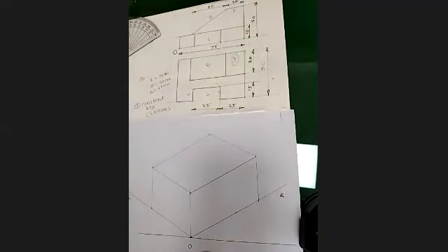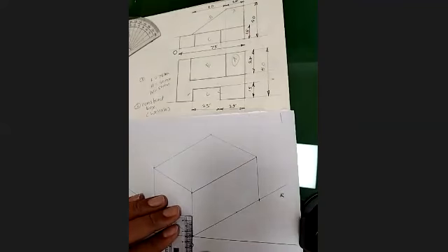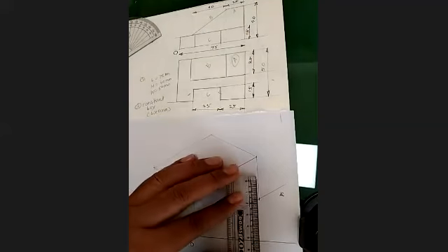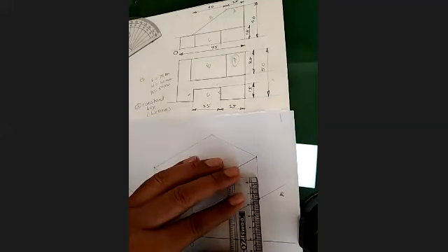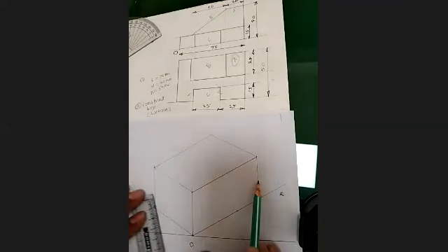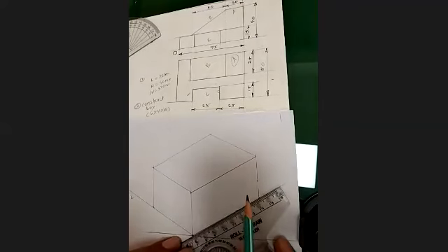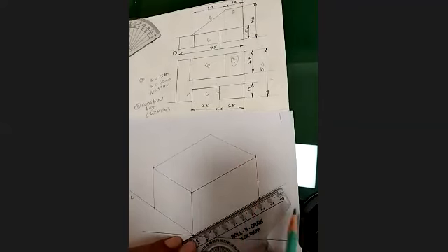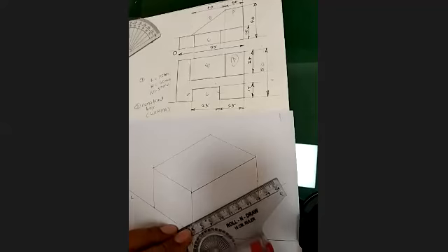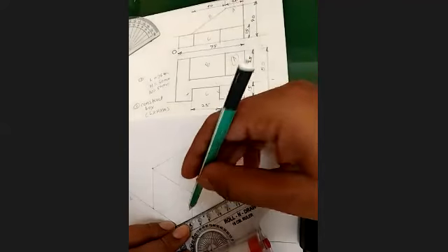So what we'll do, we'll take the 15 millimeter from the base. Of course, if you take it from even here or on this, if you take 15, no matter. You take a 15, have a point marking for 15. Then draw a line parallel to the right axis through this. Draw one light line.